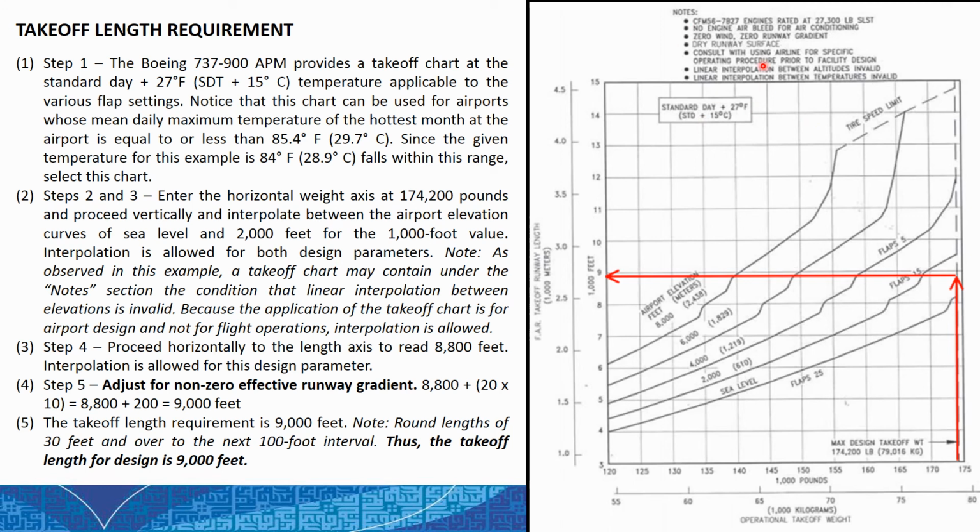Basically, the landing length requirement also has its notes, and for both charts, the takeoff length chart and the landing chart, the conditions are zero wind and zero runway gradient.